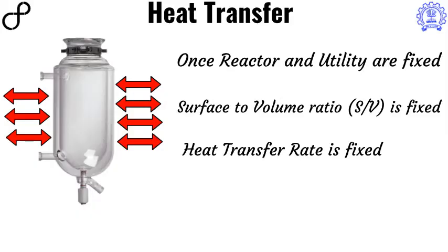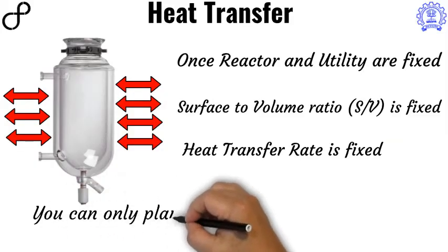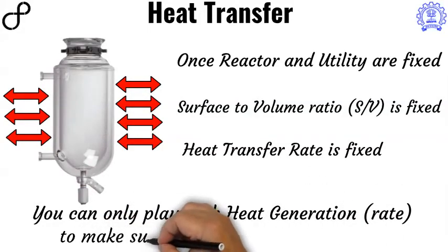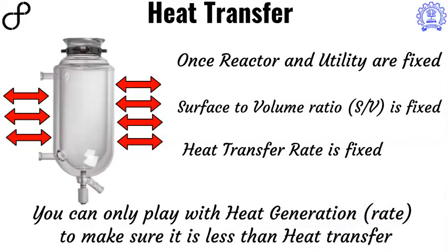Now, for any controlled process, I have to make sure to control the rate of the reaction such that the heat generated per unit time is less than the heat exchange capability of the tools used. This is the most critical parameter which process engineers have to keep in mind. If this is violated, it will lead to runaway reactions and hence accidents.